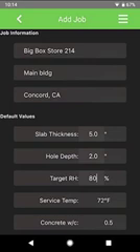The service temperature and water-to-cement ratio are used to estimate RH readings that would be expected were the slab currently at service conditions. This would be the case when readings are being taken when the slab is not already equilibrated to the service temperature and relative humidity, for instance, when the building envelope is still open.